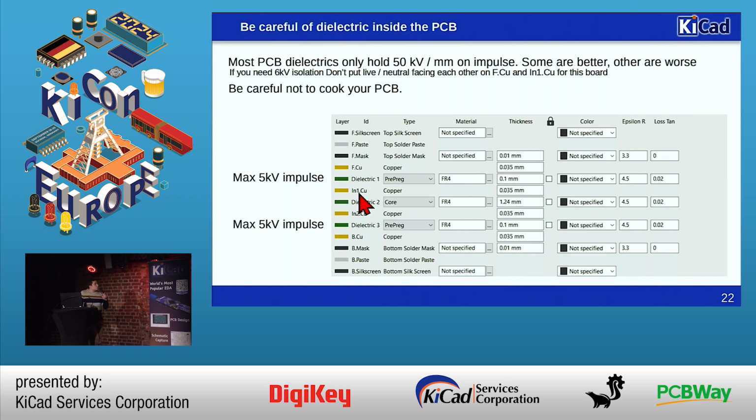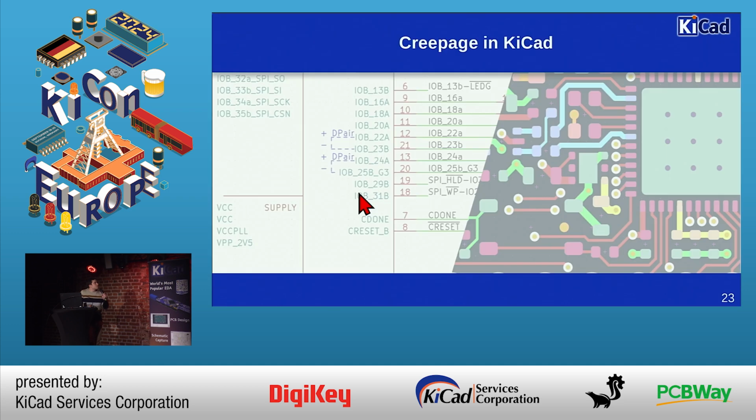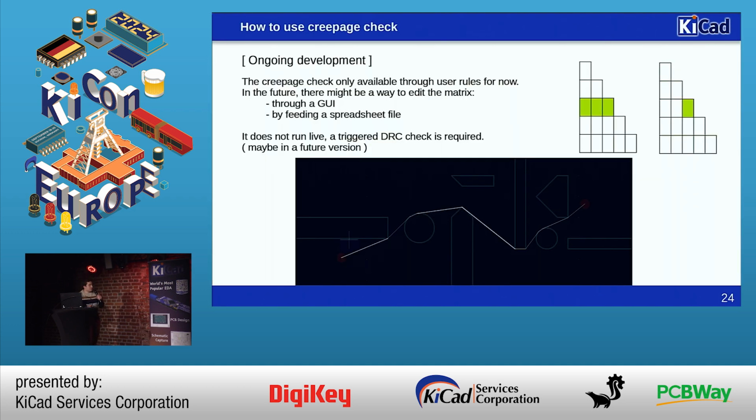That's pretty much all for the clearance. Now here comes the creepage. There's no creepage check at the moment in KiCad, so it's an ongoing development. At the moment, we can only set it by a user rule, like this one, so only to pinpoint a single cell. But maybe in the future, we might want to have something like this, to set it for the entire net class.